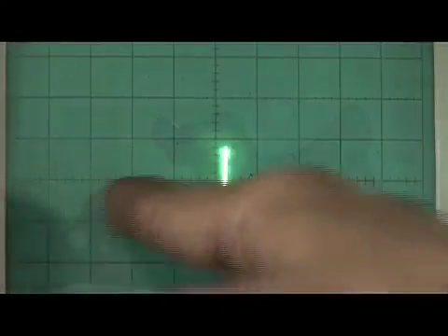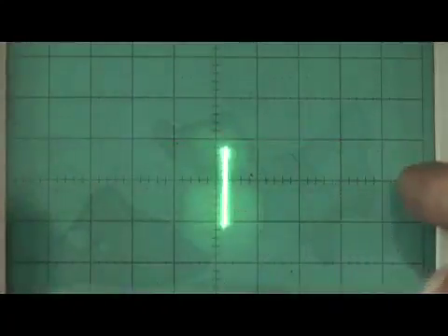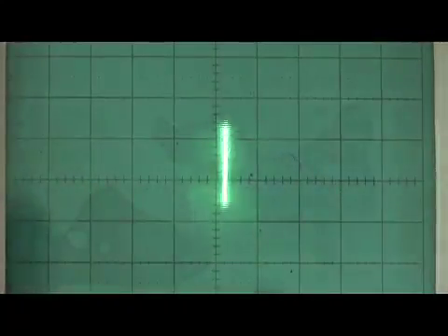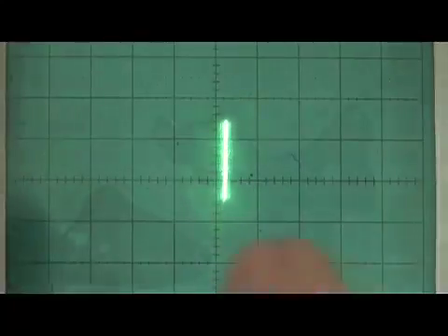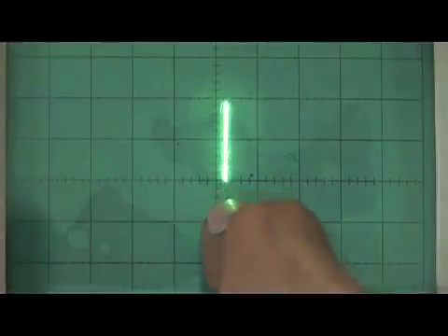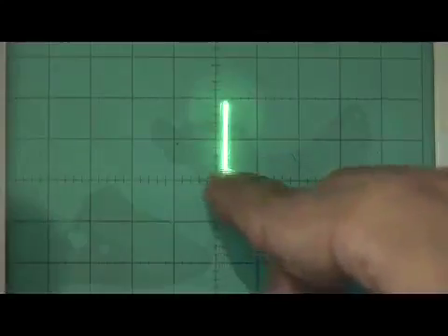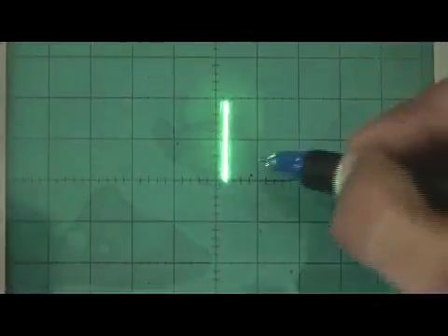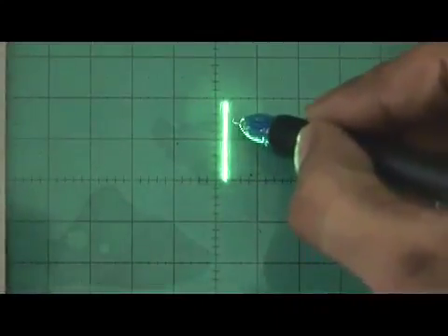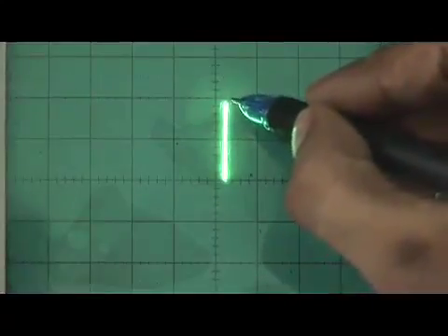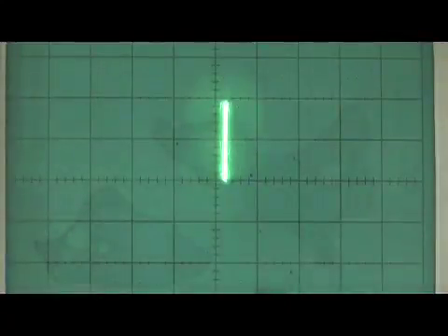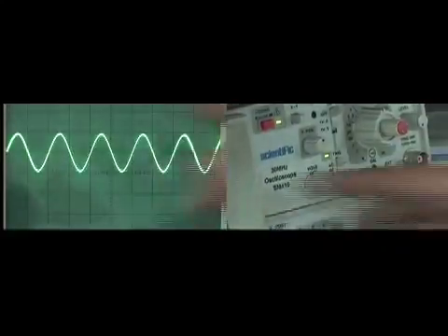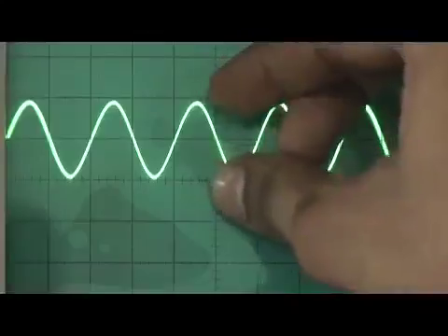Now this dark black line, which has subdivisions, is your reference line. Using this y position knob you can move this line and bring it over here so that you can properly count the number of divisions. Now it is here. From here, if I count, it is complete till here, 1. From here it is 1.2, 1.4, 1.6, 1.8. It is almost touching 2 but not 2, so let us take it as 1.9. I release the XY. So it is 1.9 blocks that it is taking for this amplitude.